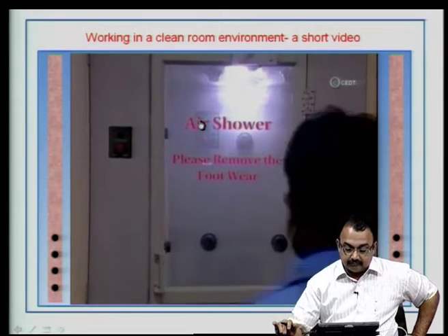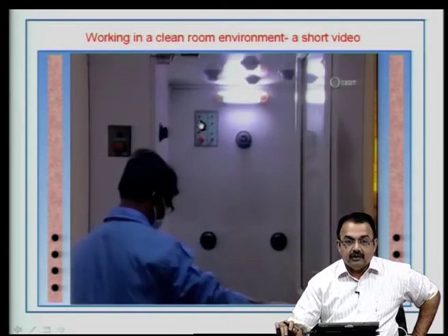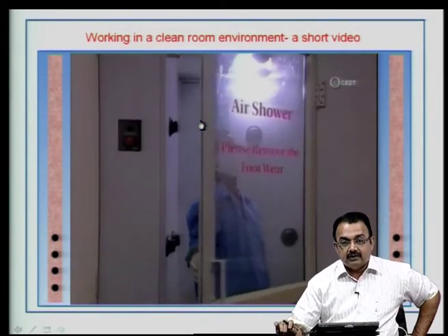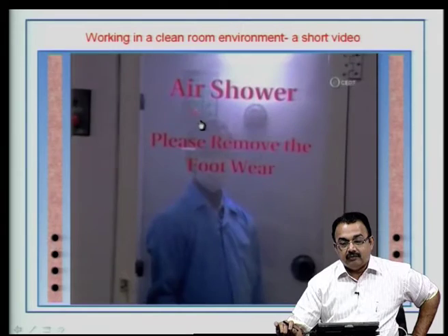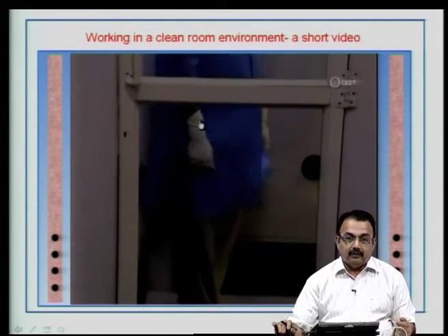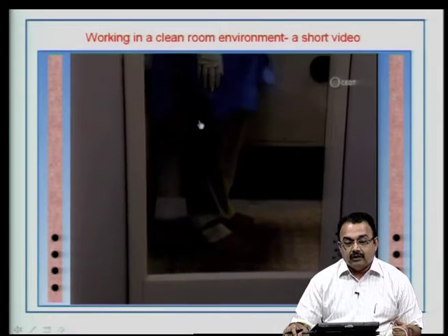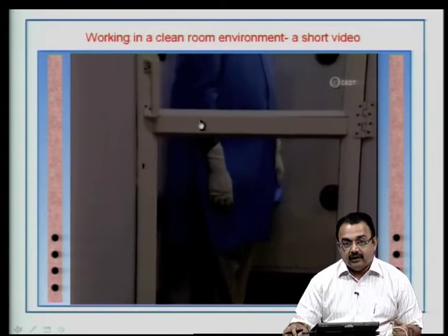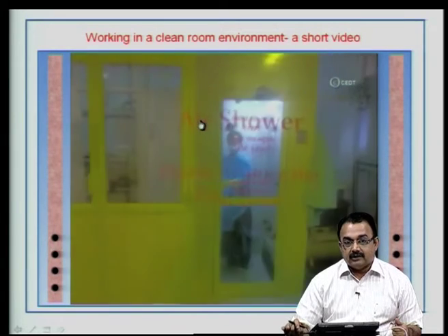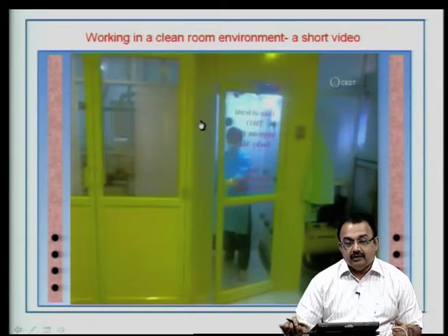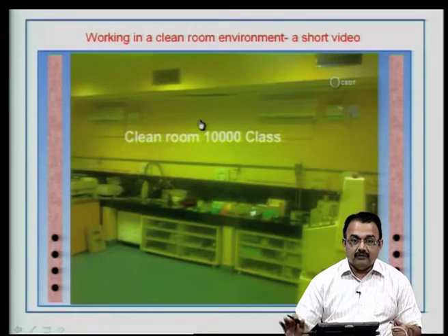Normally, in a lab or a manufacturing setup, there will be an air curtain and also an air shower. Any personnel entering the lab need to have an air shower. The air shower is used because it will blow away all the dust from you, from your hair, from your clothing and so on, and this will prevent the dust from entering the lab, because as I said, a speck of dust falling on the surface of the PCB is going to get translated along with the design.